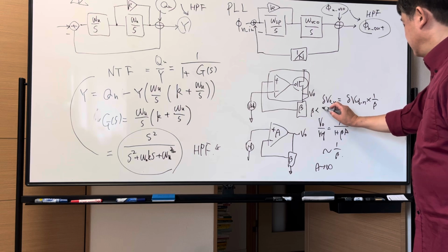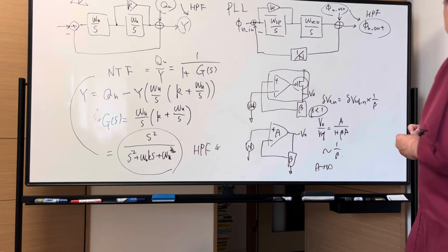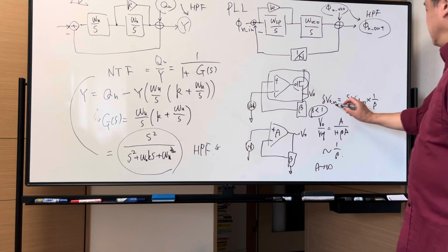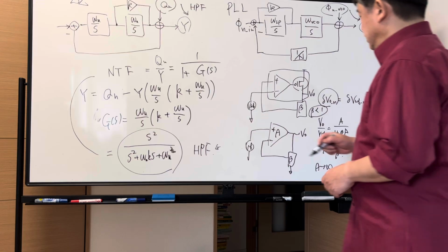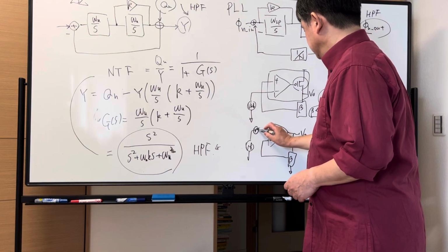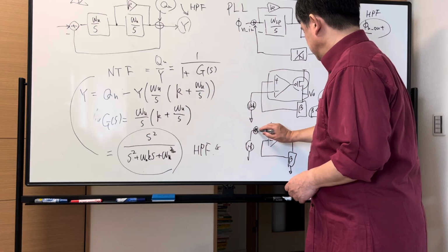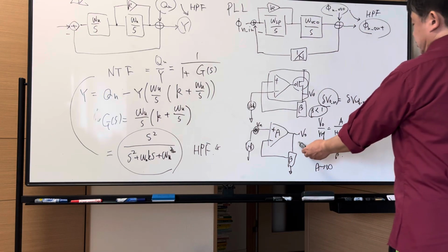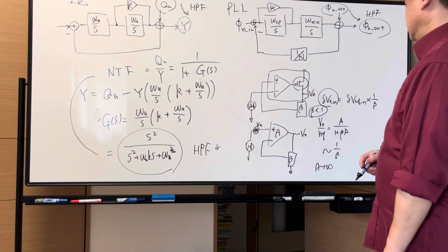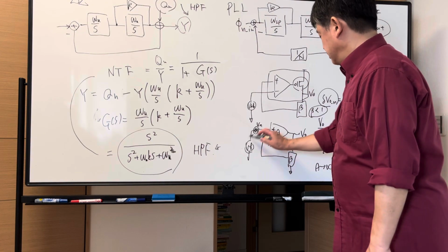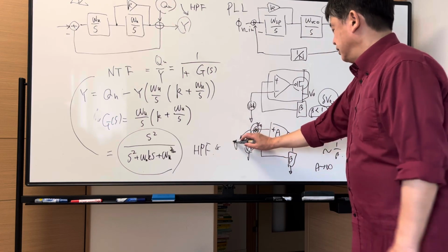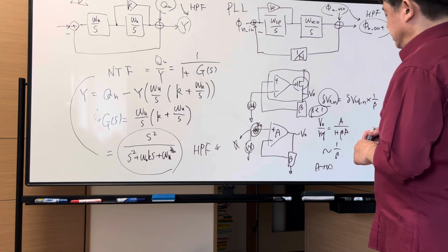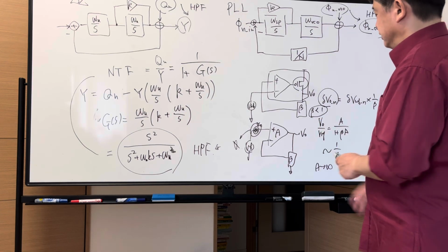Beta is usually less than 1, of course. So this is multiplied by some gain and generates output noise. This input noise multiplied by this gain makes output noise. And if this noise is decreased enough to be neglected, it's very good for the LDO output noise.